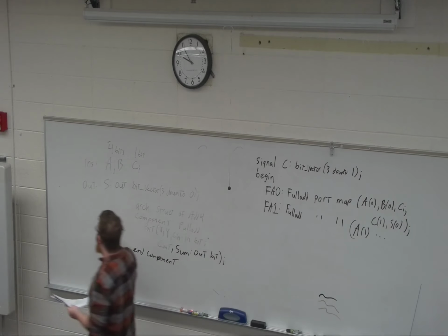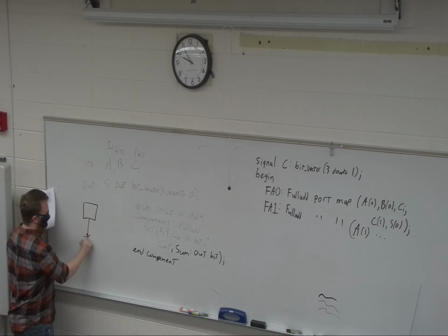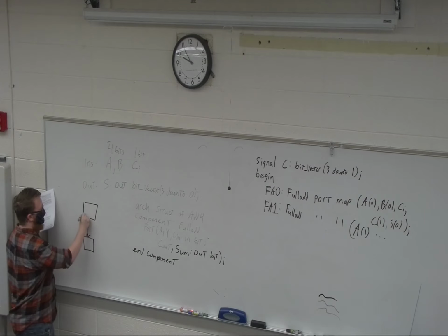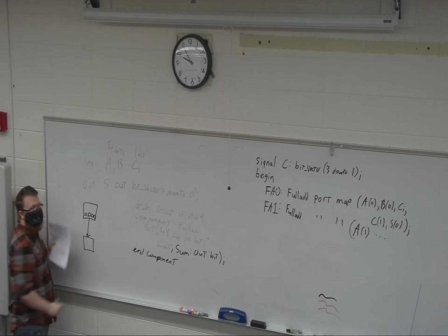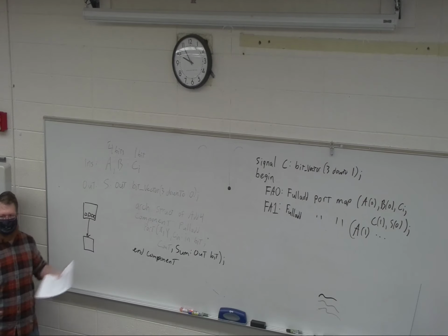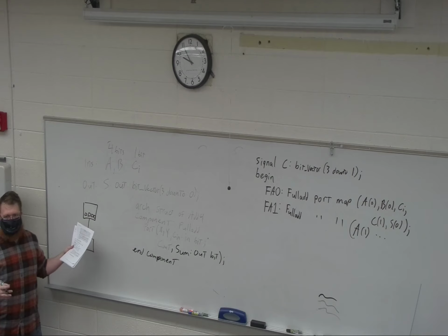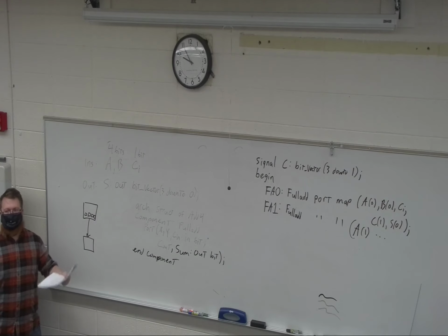Right, so now when I'm drawing my little block diagram that's going between things, I have to start considering that I've got a couple little sub-modules inside of that. And you can start cascading those quite a bit. So we call this hierarchical design, right? There's a hierarchy to this. And you can put them all in different files, which is really nice. You can even build whole libraries for yourself in VHDL like you do in C and Python.